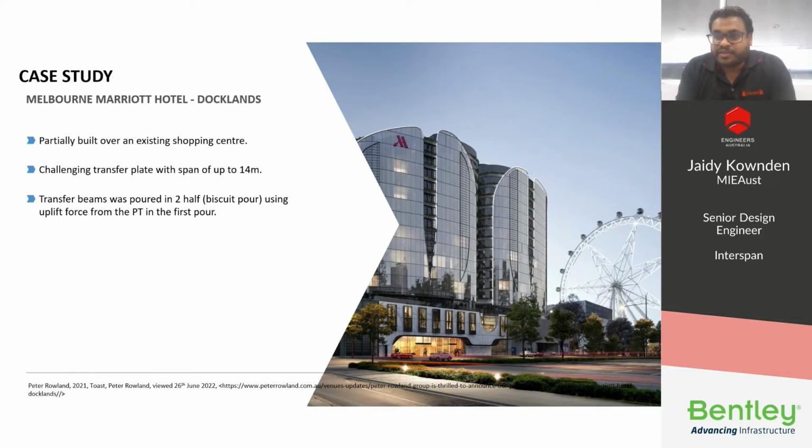One of the biggest spans on the transfer deck was 14 meters, something that would not have been able to be achieved at the same depth using a conventional deck. Given that there was a building below it, there was also a limited amount of backpropping that we could use during construction. And to help with this, the transfer beams were poured in 2 phases. The first pour was used partially to support the second pour using the uplift provided by the PT force.